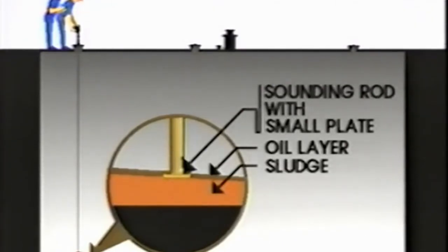If there is a discussion about ROB and the dip clearly indicates liquid, use the wedge formula or wedge table to calculate remaining cargo. If the dip indicates sludge or sediment, you should also suggest using the wedge formula to compute ROB.